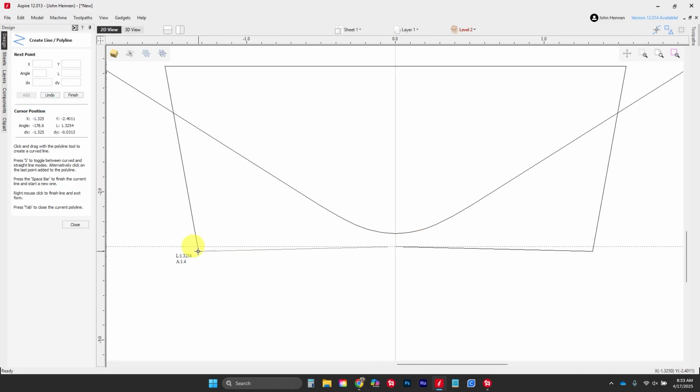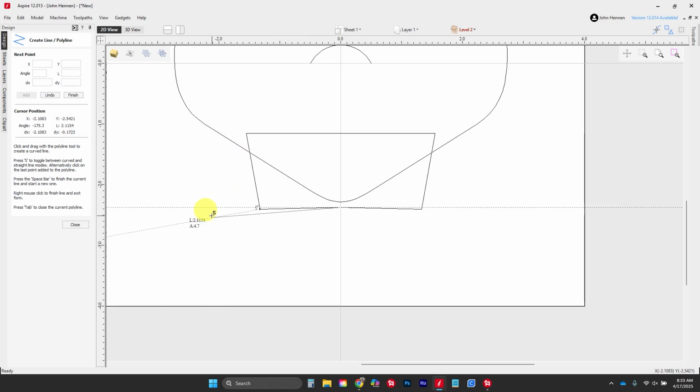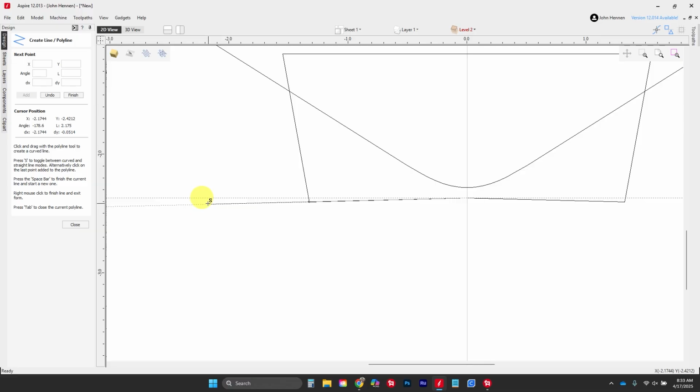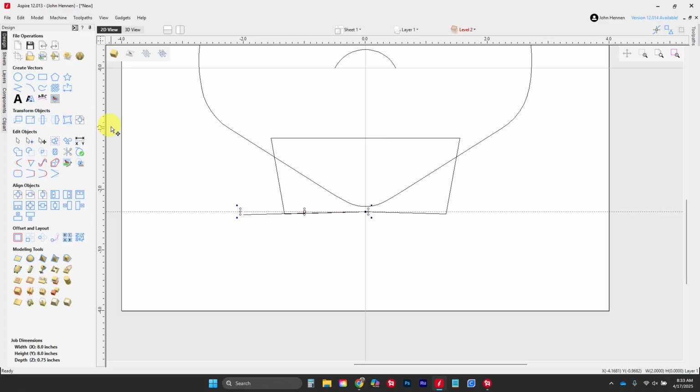We're going to come down here, and I want to come beyond it because I'm going to have to make sure I'm beyond it long enough that it can come up here. If we look at that length, it's 1 3/4. So as long as I'm out here, let's go 2 inches long. There we are. That's going to be plenty long. And we're going to go one more time from there to right there. And we're going to build our little waves again.